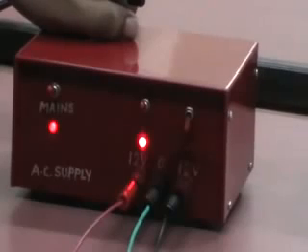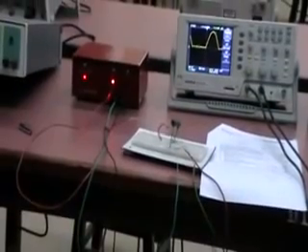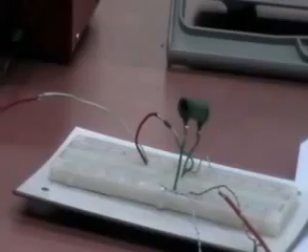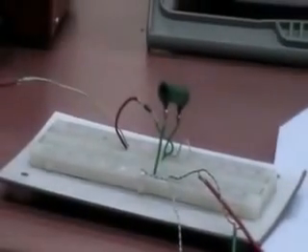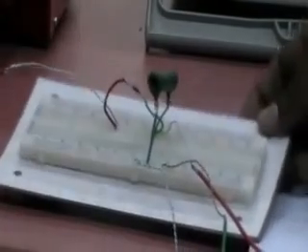Okay. So this is the step down transformer that we are going to use in the rectifier case. Coming to the half wave rectifier part, the circuit interconnections are done according to the diagram. As you can observe in the manual, in the positive half cycle, the diode will be short circuited and the input will come across the output. In the negative half cycle, it will be 0. The circuit can be seen on the breadboard.